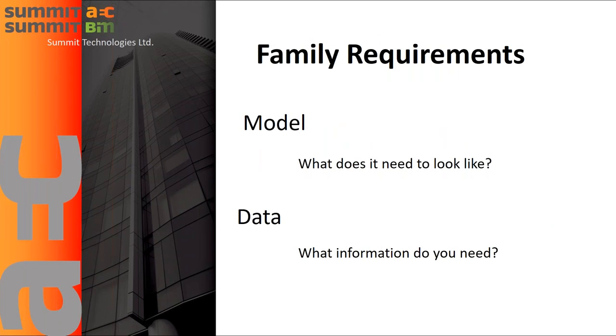Okay, so now we're going to talk a little bit about the family requirements. Whenever you're about to create a family, you need to think about the modeled requirements. So what does it need to look like? And this isn't just 3D and in real life. You're thinking about what does it need to look like in all different views, plan, section. And then the data portion: what information do you need to have in that family? And then working out whether or not you need to grab data from the family, so the output.